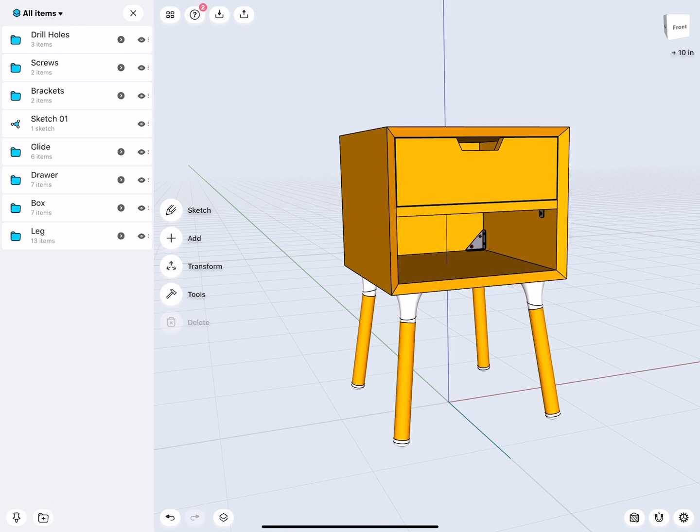Oh, good question. STEP or IGES? Honestly, it doesn't really matter. From my experience, however, while they're both kind of like very similar, most people seem to prefer STEP compared to IGES, and I think sometimes that comes down to compatibility and also quality of the geometry or the data that's inside. And STEP seems to be a little bit more of a stable format, but essentially they're more or less the same with different flavors.